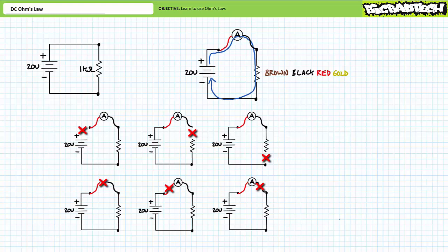Having determined an open as the source of your problems, it's now up to you to find it. Oftentimes, one needn't resort to instrumentation to find the source of the problem. Just look at it. You might find a wire dangling out into empty space, or a component or wire misplaced or landed on the wrong spot. Attention to detail in viewing the circuit from several different angles might reveal the cause for the missed connection.